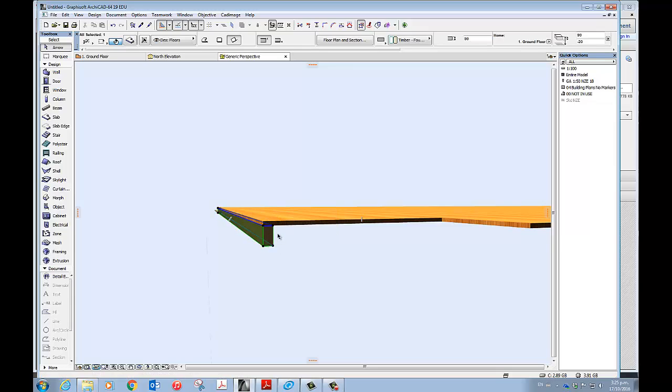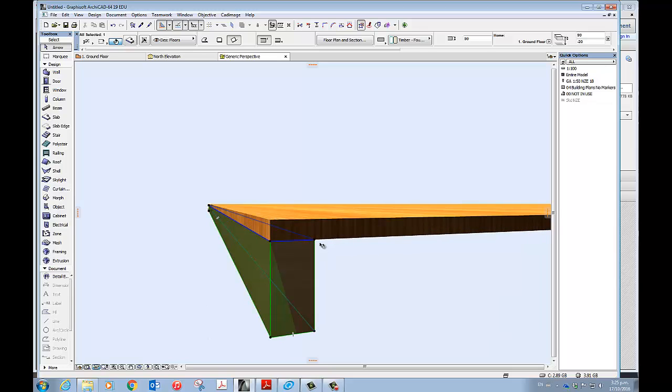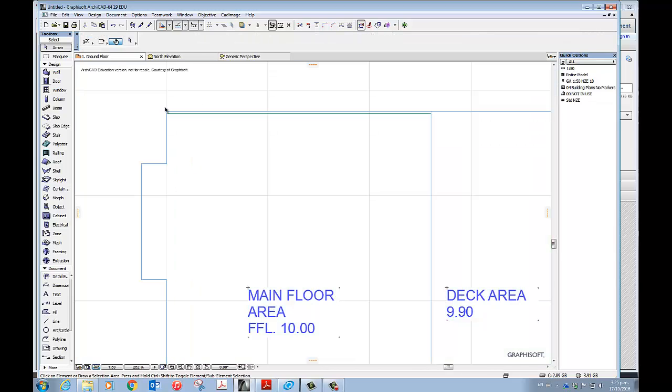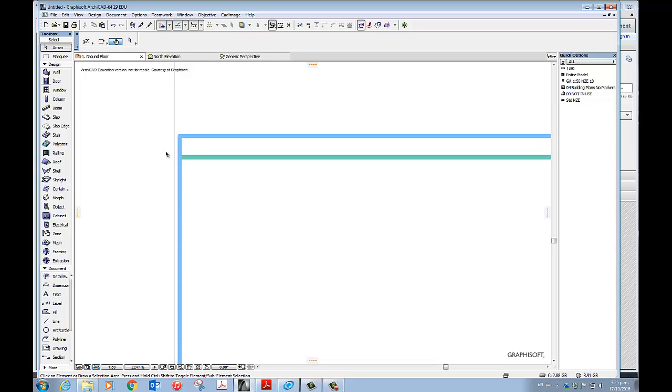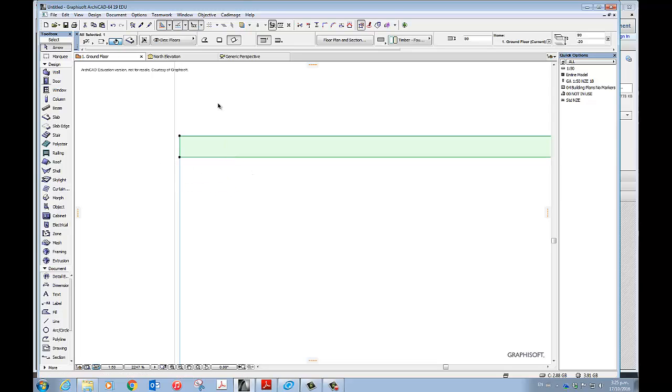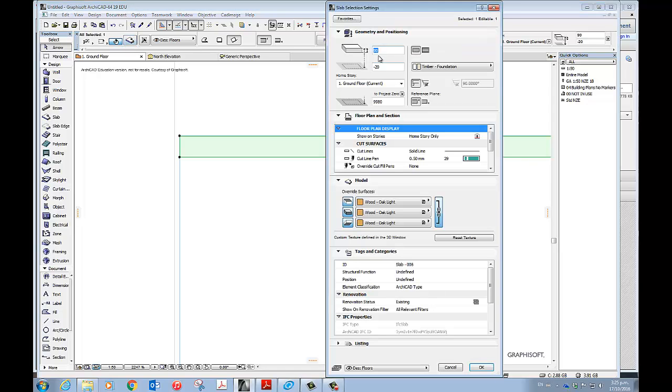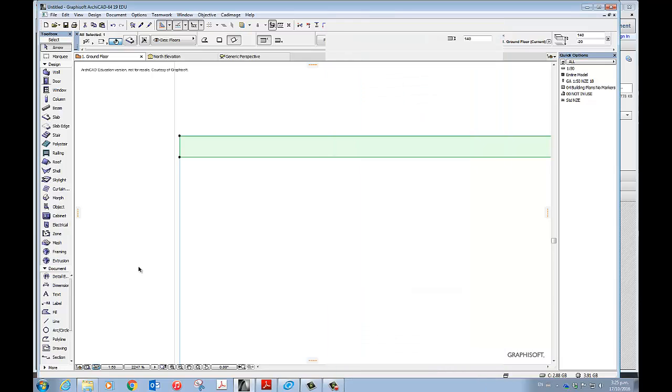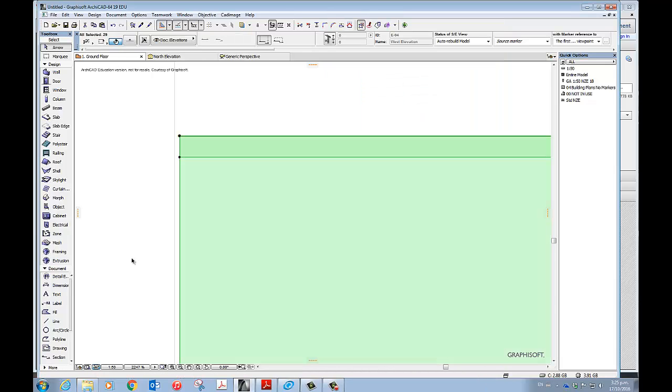It looks rather wide, so I'm going to go back and check the width of that, but the important thing is that it's actually below the flooring. I'll go true line weight and hit measure from here to here, 45. I guess it's because that joist is quite small, so I'm going to make it deeper. I'll just make it 140 and keep it where it is. And let's have a look at that again.